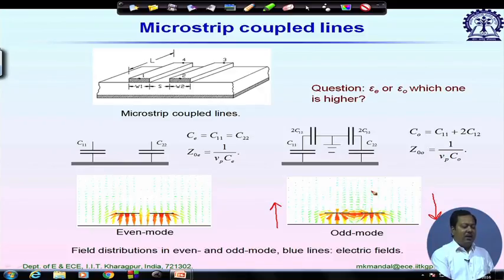This figure shows the electric field from the right to the left strip. So, we can model this system by three capacitors, C11, C22. In addition to that, due to this electric field coupling we can represent it by two more capacitors, C12 twice. Actually the capacitance is C12, we are just breaking it into two parts.